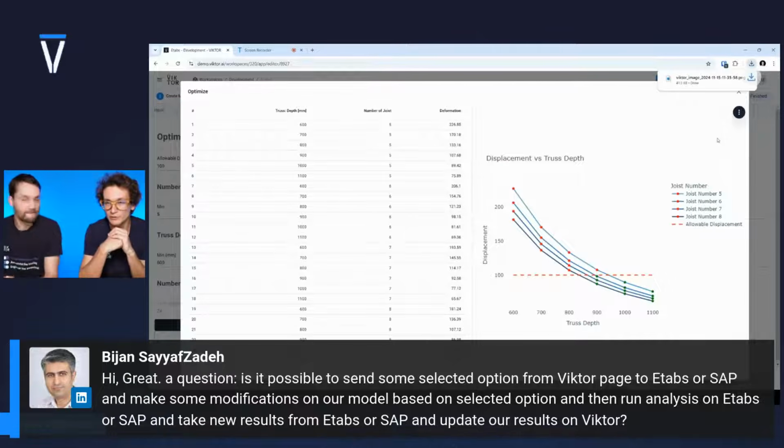Whatever your case is built on, it depends how you want to target your API. Because with VIKTOR, you can interact with any API call that's available from ETABS or SAP2000. So a typical case is that last minute, you get an email from your geotechnical engineer, and you have to change the foundations and the spring stiffnesses. You could upload your model, change that in your model, run it, get the results back, show it in your nice visualization, calculate the foundation again, do some optimization. So you can do whatever you want with it.